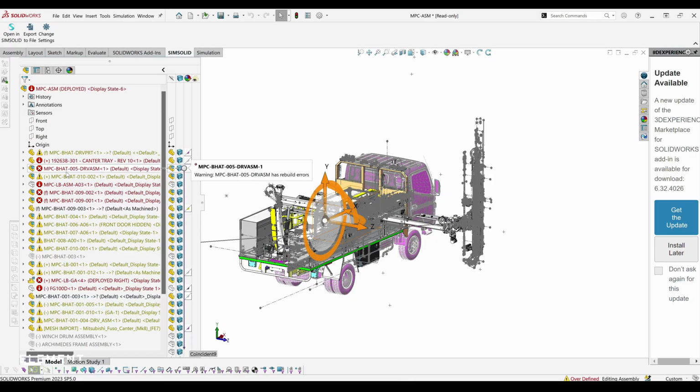Here you can see another good modeling practice, which is making sure you're using assemblies or sub-assemblies to segregate your different modules or components that are going to be manufactured as a standalone part or system. The driving part has a bunch of sketches that are driven off other sketches and define all of the geometry of an entire model. From there, we'll build up parts within this assembly model, or sub-assemblies of parts. To do CAD really well, especially in a multi-user environment, you should be segmenting an area of the product into a sub-assembly, and the driving sketches should really be defining just the outline of those things. The top-down modeling defines the overall placement of things, and then the sub-assembly may have some specific sketches detailing things within that.